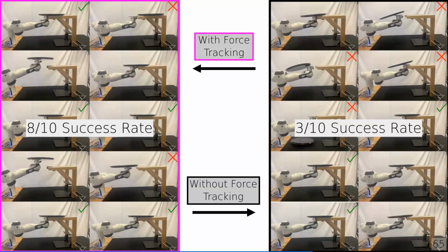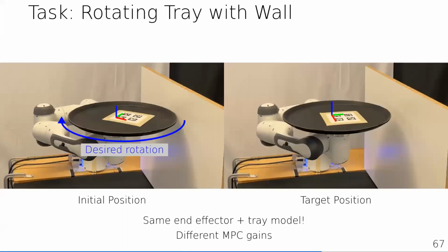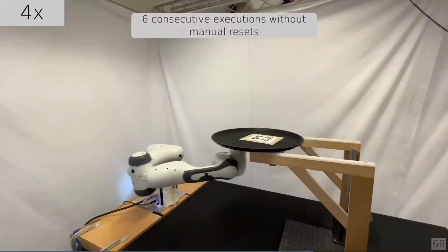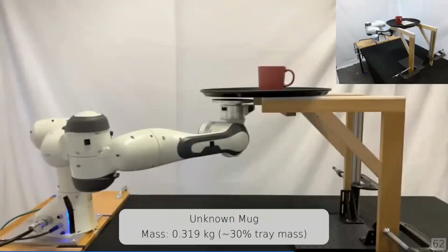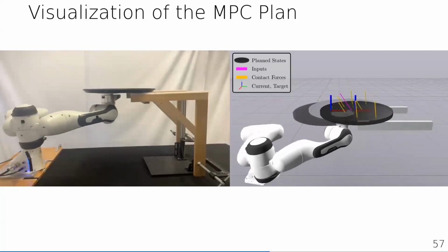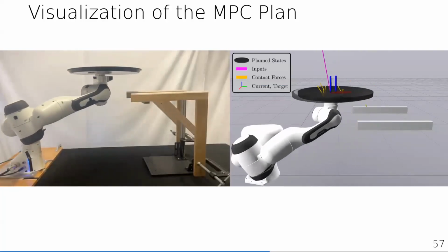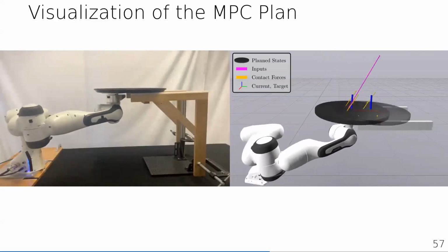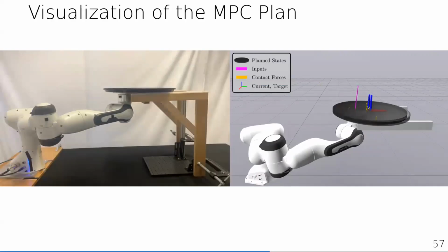That's the reason why we had 2 different sets of gains, because we're really just choosing a specific local minimum. In practice, it's very sensitive. Even for this experiment, it takes a very specific set of gains to get this behavior, because we're really just choosing one local minimum from this nonlinear problem we're trying to solve. The gains I picked make it dynamic, and the rest has to make sure it even converges to a reasonable solution. It's a bunch of gains.